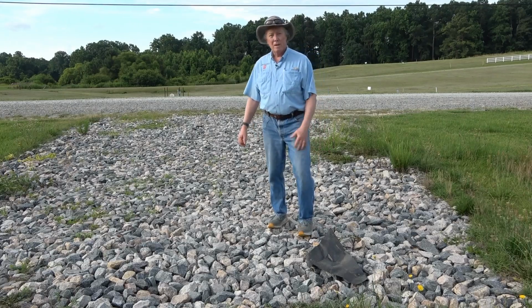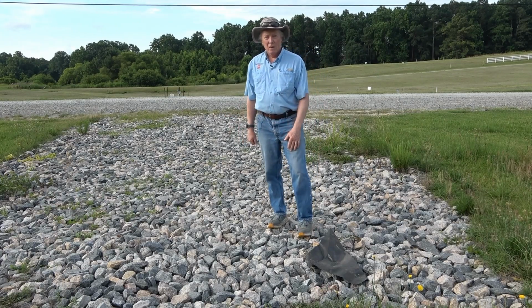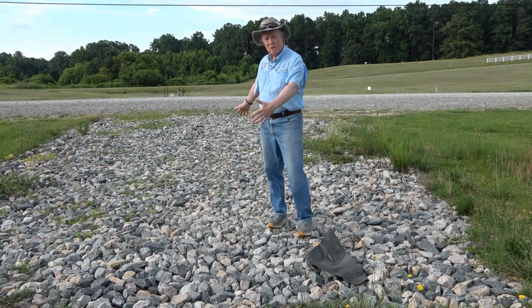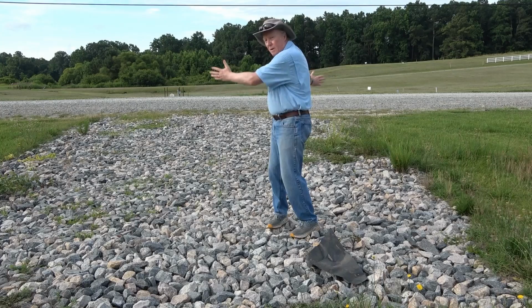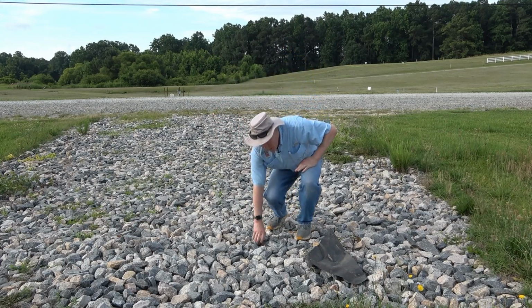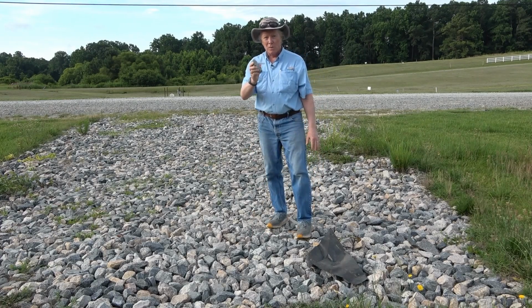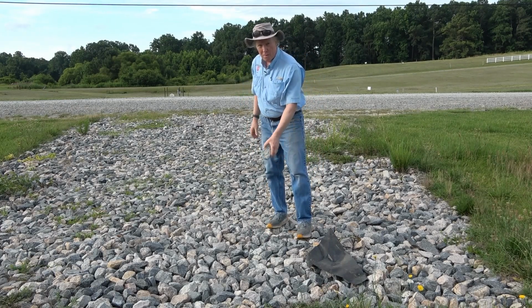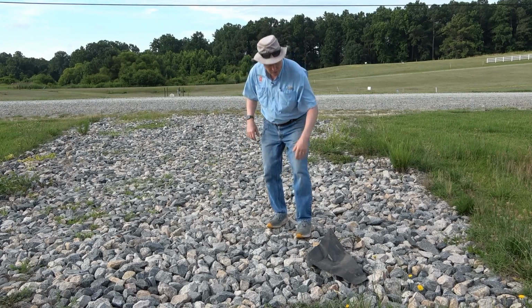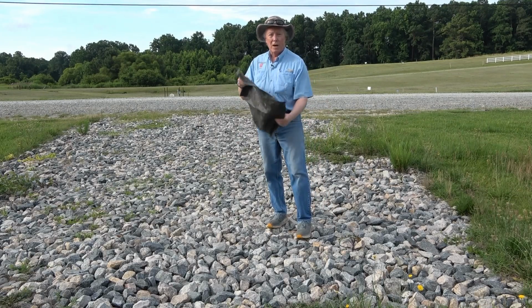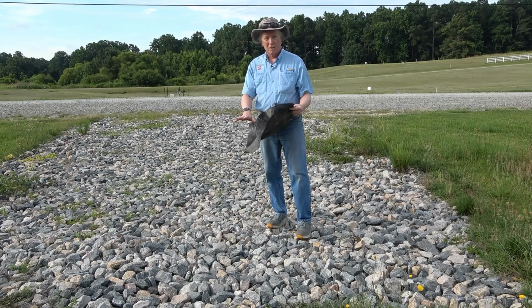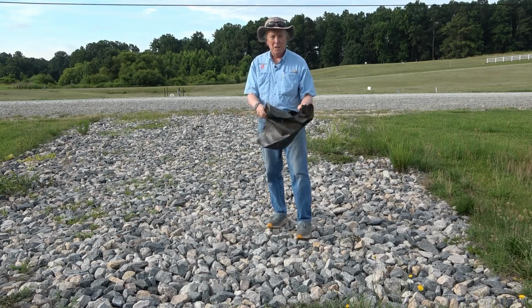All right, so we're looking at a construction entrance pad. Remember from class, the key features are they need to be at least 50 feet long, 12 feet wide, have to be flared out by the road, and we have to have 8 inches of Class A rock, as you can see here, not the large rock, but the smaller of the 2 rocks we talk about, 3 to 5 inches in size, and we need to have a geotextile material underneath the rock. If you don't do that, then generally the rock is just going to get pushed down into the soil. So we want to have something underneath the rock.